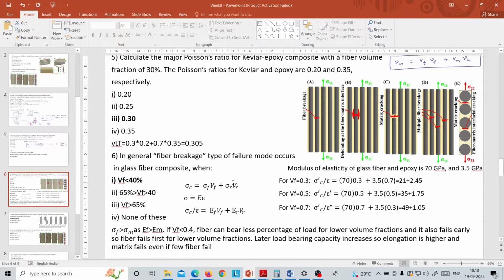If we further solve this formula, the stress can be converted into the Young's modulus of the material times the strain, as Young's modulus is stress divided by strain. We simplify this formula, substituting these stress values in this equation, so this equation will turn out as follows.